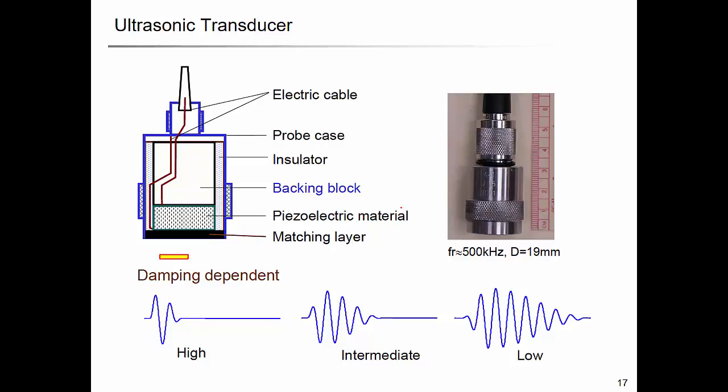This is a coaxial cable, and this is an ultrasonic transducer. Inside it has the piezo material, and you can see that outside is the shielding, so it's the negative. Outside is the shield, and inside you have the core line that applies the voltage. Let's circulate it.